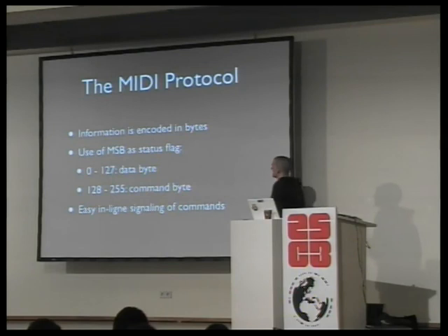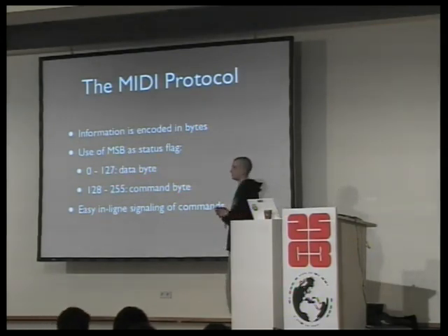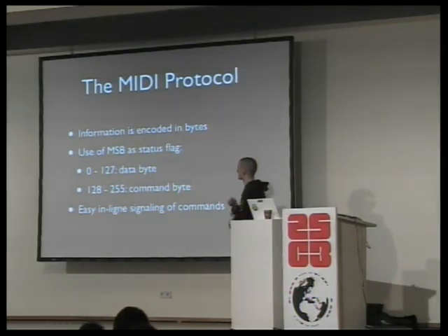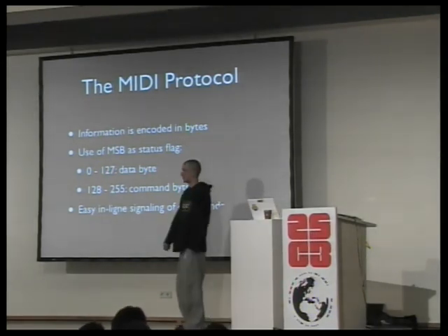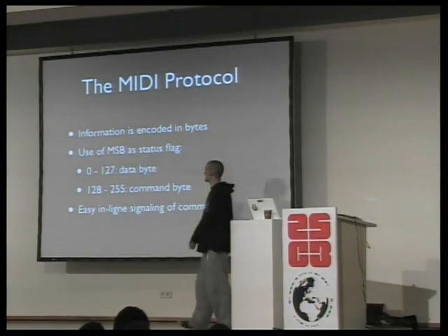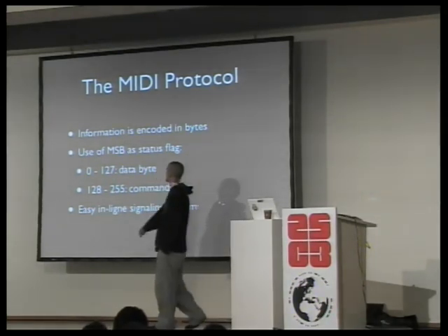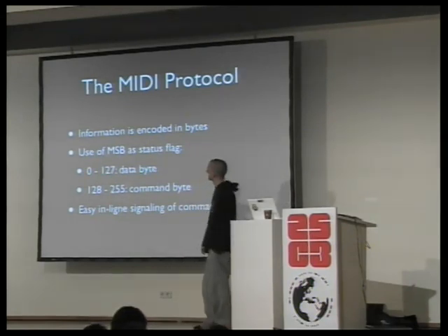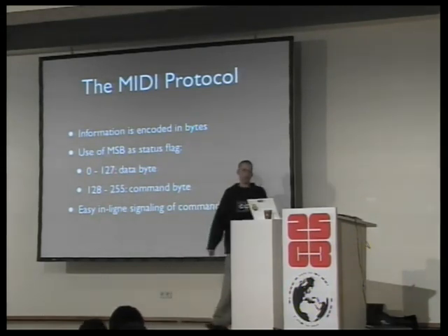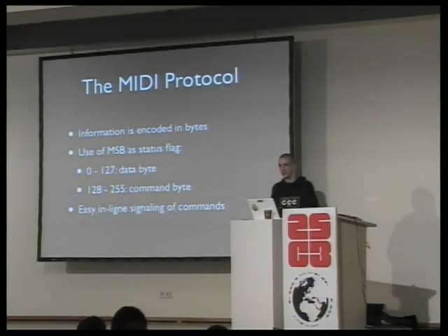So the MIDI information on the cable is encoded in bytes, but there's one slight trick: the most significant bit of that byte is used as a command flag, so you can do signaling of commands. So all these values from 0 to 127 are data bytes, and the rest are command bytes. So it's pretty easy to check if you just received a command or some data byte.